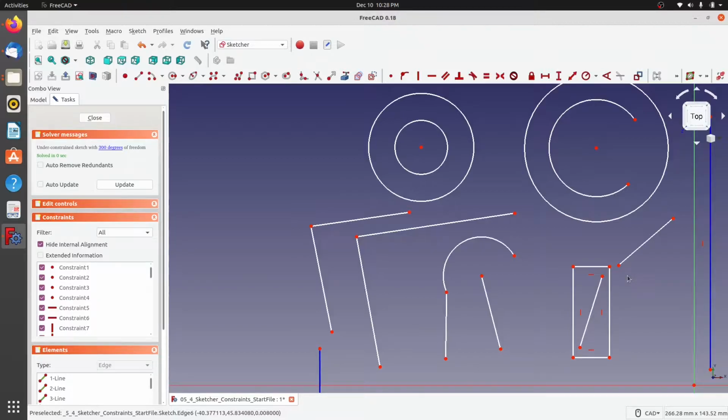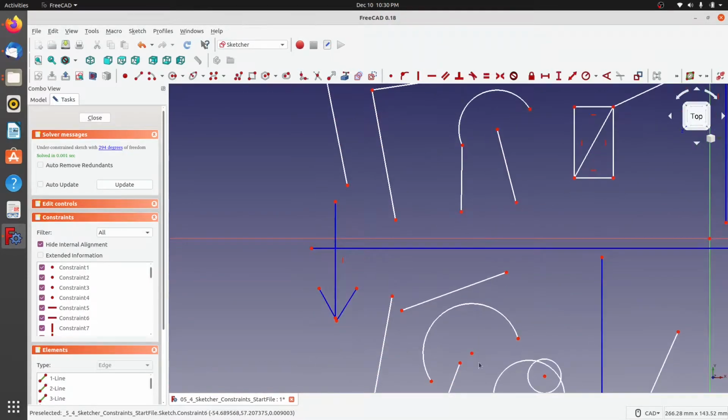Now the other way of creating a coincident constraint is if you want to join this line segment, so this end of the line segment with this corner of the rectangle, again clicking on the coincident button will make these 2 points coincident. Similarly, how about we make this point coincident with this point on that edge, and then this point coincident on this corner. So what effectively happens now is you can move this whole square or rectangle by just clicking and dragging on the line that we just connected with 2 of the edges or 2 of the corners. So this is all about coincident constraint.